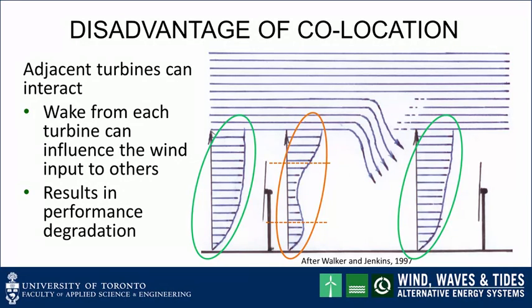You can see from this illustration that it would not be a good idea to place a second wind turbine too close to the first wind turbine in the downstream direction, as the second wind turbine's output would be significantly reduced as a result of a reduced wind speed profile like the orange circled one shown. So, spacing between turbines is important for laying out a wind farm.